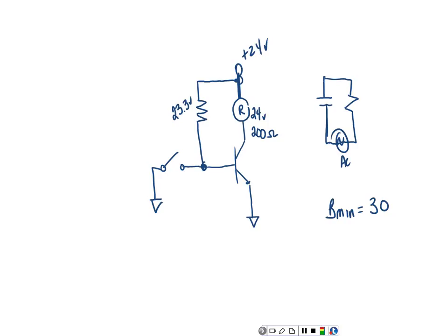So somebody tell me, what's the first thing we're going to do? We're not concerned with the transistor cut off. We're concerned with what goes on when the transistor cuts on, right? You understand? So how much voltage are we going to say the transistor drops when it's cut on, if it's acting like a saturated switch? We're going to assume it's going to drop approximately 0 volts. It's going to be a little greater than 0, but it's going to be less than 1, right? And a 24 volt relay would work fine on 23 point something volts.